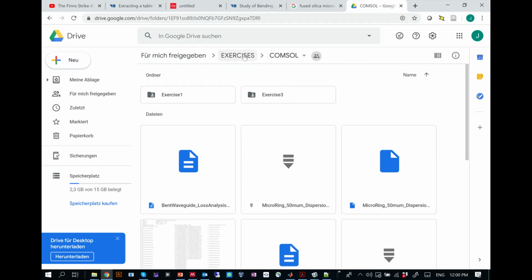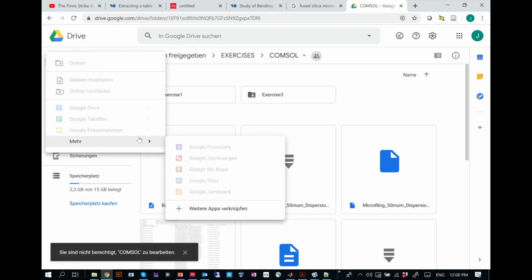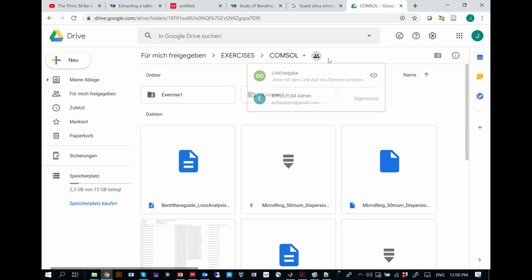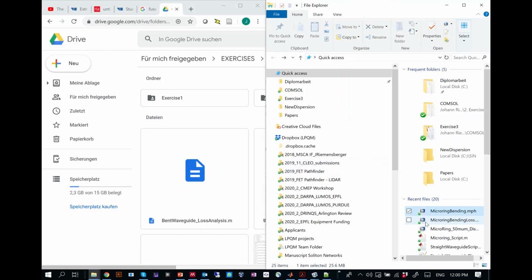Exercise 1. So we have 3 exercises. The first one is more or less numerical, to study the convergence: how your solution depends on the field size and the mesh size. That's why we parameterized it. We made these parameters of field and mesh, and now we can study how the solution depends on which mesh you use, fine, extremely fine, and for which frequencies. You have to choose which mesh and field size because it also depends on your frequency.